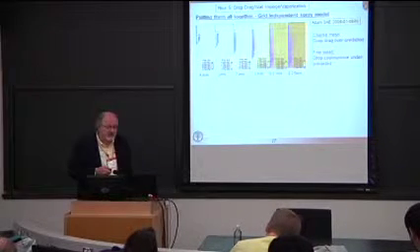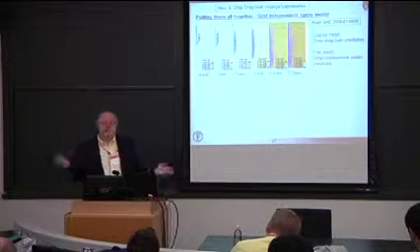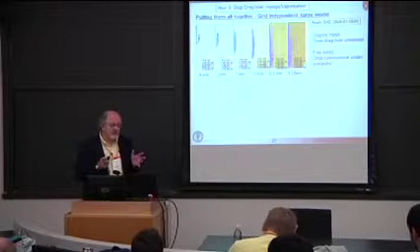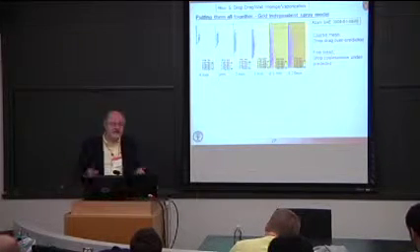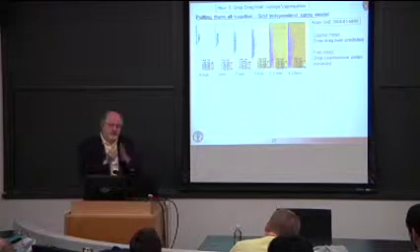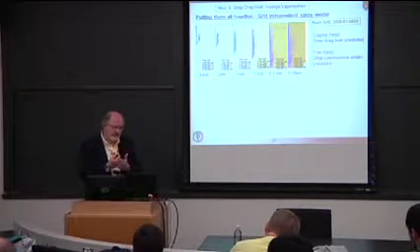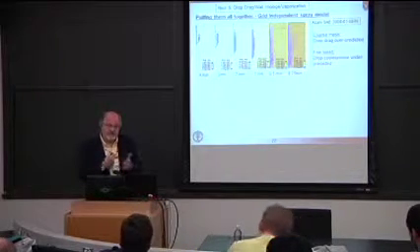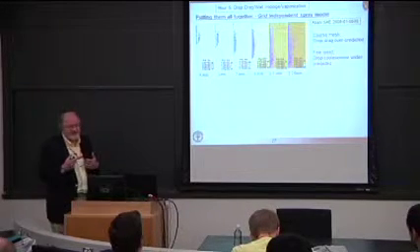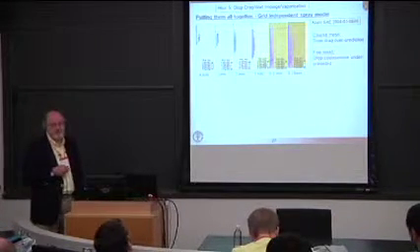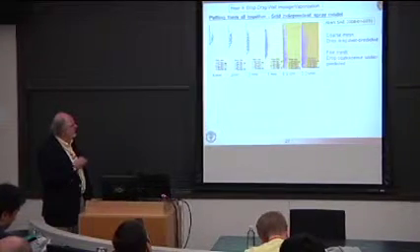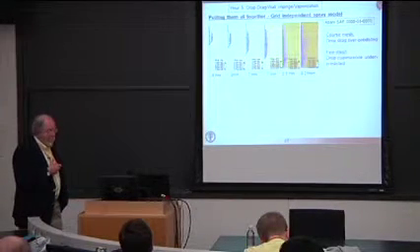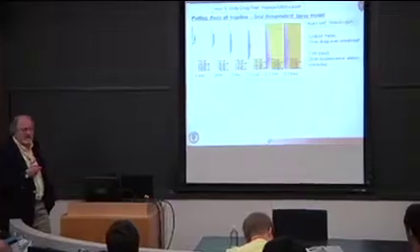over-predicted. Essentially, if I have a cell the size of this room and I throw a droplet in this room, according to the sub-grid scale model, that droplet has to give up its momentum to all of the air in this room, so it slows down rapidly. But if I have a tiny cell, I send that droplet into the cell. The air in that cell basically is much less air that has to be accelerated or decelerated. And so I see a different effect depending on the size of the computational cell. So this is a big problem, especially in the air injected case, where the droplets are, as we indicated before, not really filling the cell.